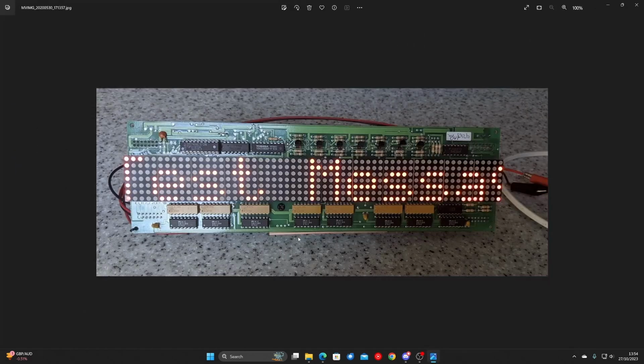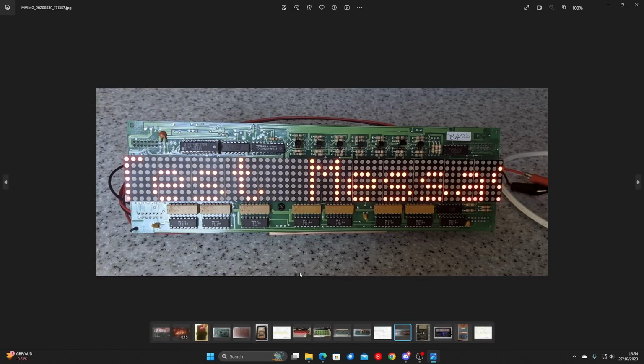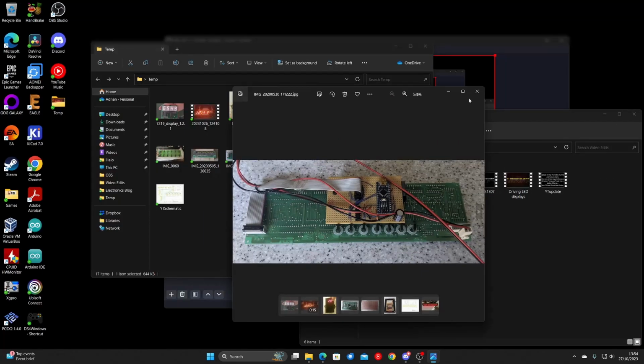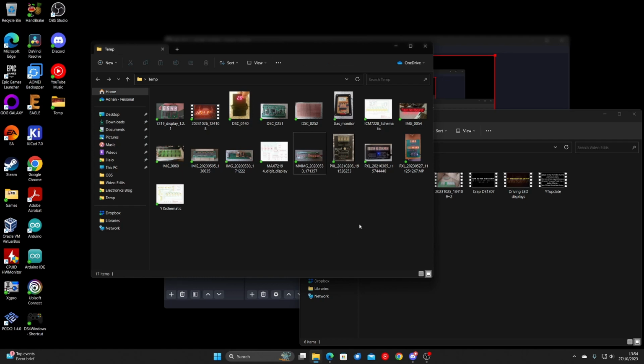This thing here is an LED module from a cinema lobby board, which I got during lockdown to mess about with. Basically, there's a chain of shift registers here and some transistors that select the rows. Again, I had to write all the multiplexing code, so the code for that was quite complicated. That's the rear of the module. Now, to save pins on the microcontroller, I just use a shift register to select the rows instead. But yeah, that basically sums it up.